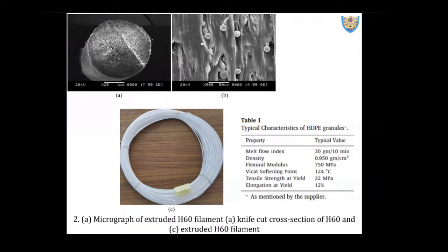The density of these hollow microballoons is 0.4, okay, intact, meaning non-broken ones. Now, if this particle breaks, this particle is made up of glass. So if the particle is intact, the density is 0.4. If the particle breaks, what would be the density? The density is going to be the density of glass, not the balloon. So what is the density of glass? 2540. So from 0.4 to 2540, it suddenly shoots up. So that's what I was talking about. The filament might sink or float based on the number of particles which survived there.